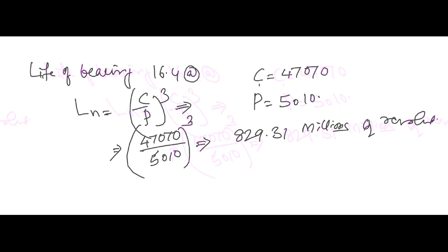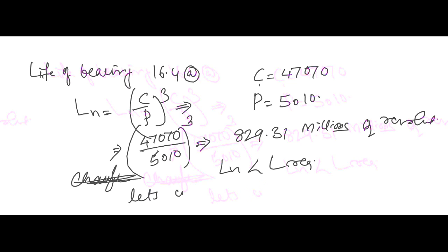Now in this case also it is not satisfied. Okay. Now you need to change the diameter. Write a comment here: your Ln is less than L required. Okay. So let us take D equal to 55 mm. Now for D equal to 55 mm, you note down the values of C naught and C. Then you repeat the same procedure.